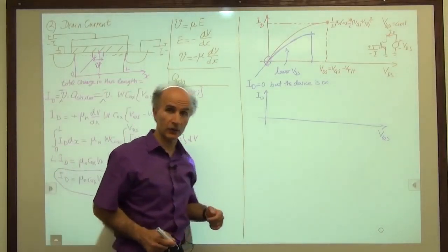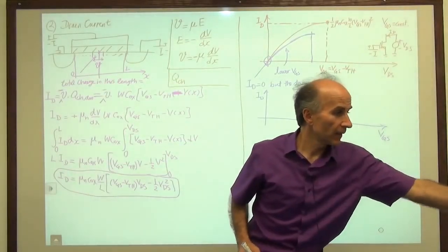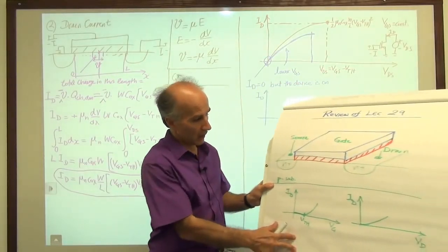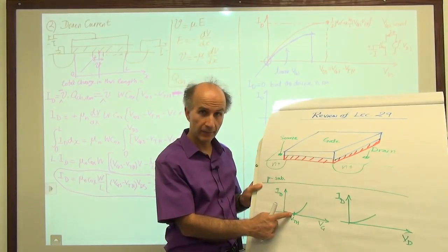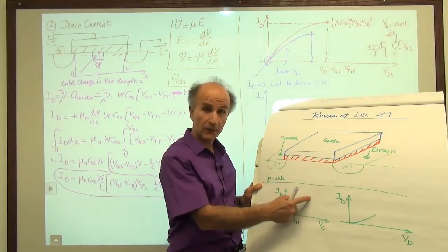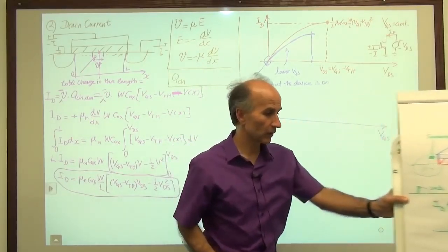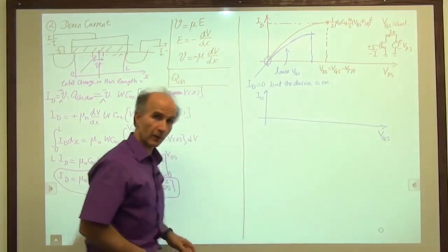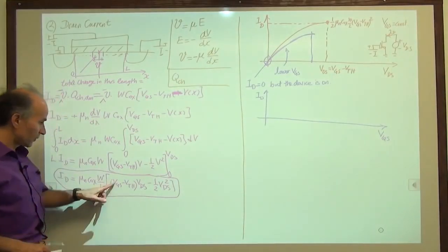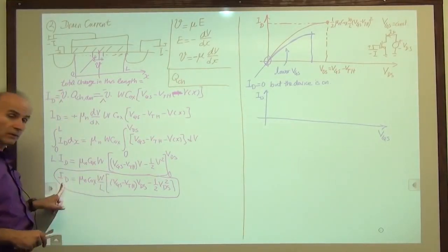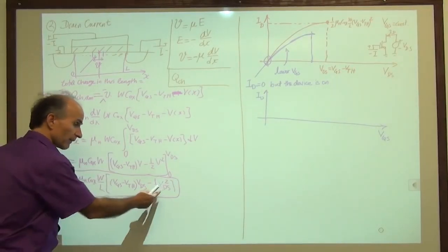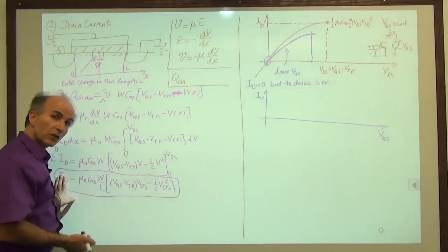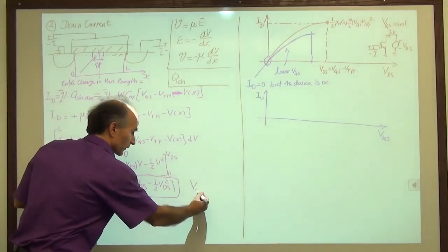All right. Well, remember from last lecture, what we discovered was that if VGS is less than a threshold, we have no ID. Right? Because there's no channel. And then it begins to take off. So is that reflected properly in this equation? If VGS is less than VTH, is ID 0? No. So it means that this equation is valid only if VGS is greater than one threshold, right?